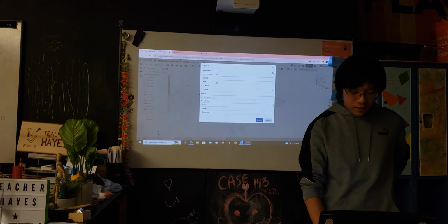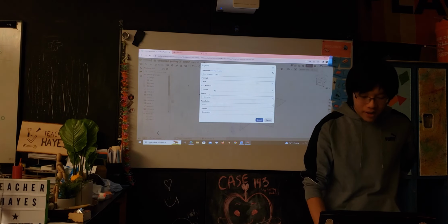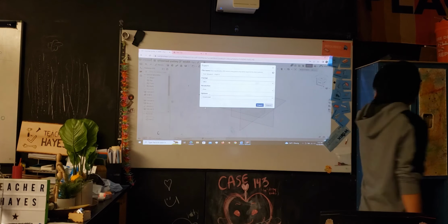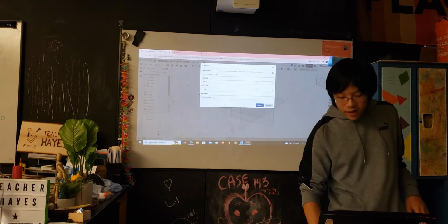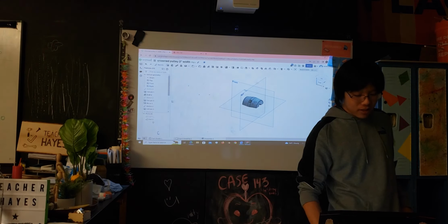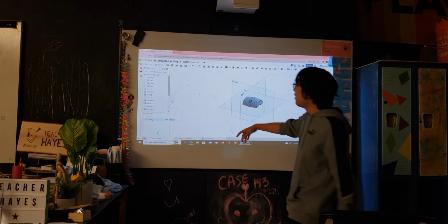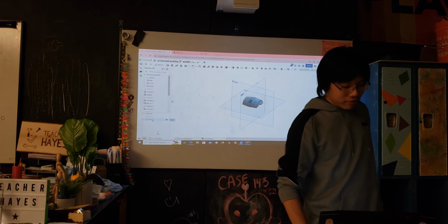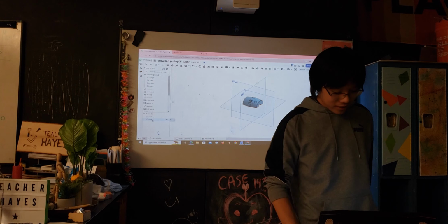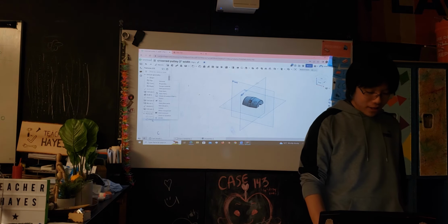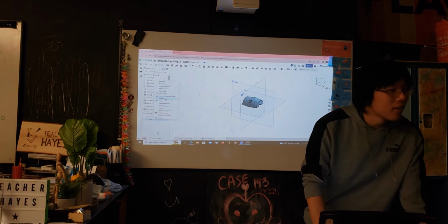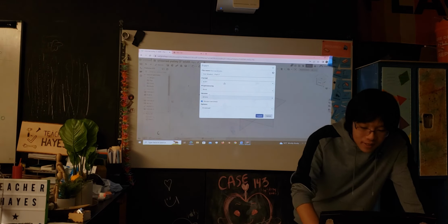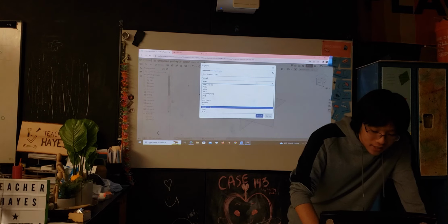We're 3D printing, so use an OBJ or STL file. What you do is go to your Onshape document, and in the parts list on the bottom left, you can click on a part. Right click the part that you want to export, or that you want to 3D print, and then you export it in format OBJ or STL.